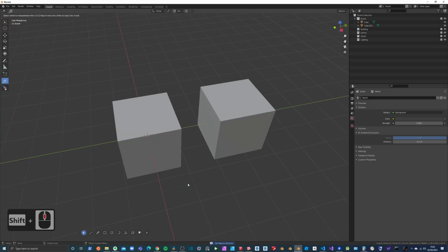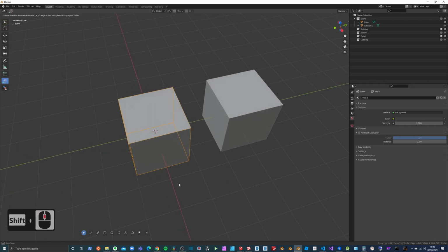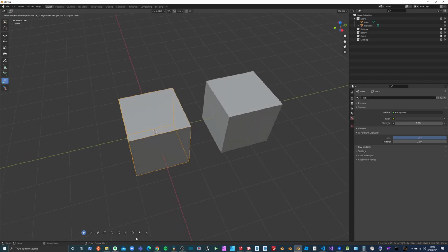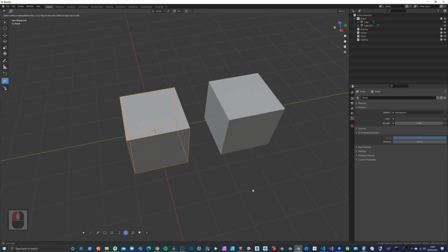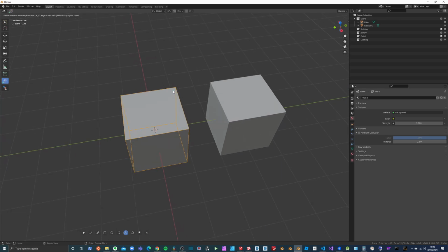What's quite handy about being able to select an object to work on is that you can now do things like take the Move tool, and instead of being limited as you were before to the snap points on the object itself to start from, you can now start your move from a distance on another object.